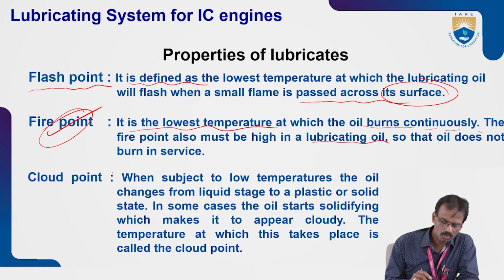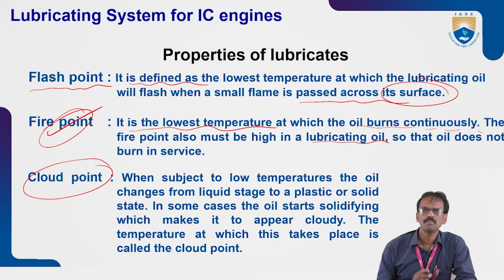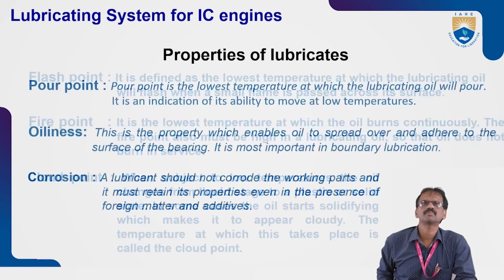Next, cloud point is also very important. When subject to low temperature, the oil changes from liquid state to a plastic or solid state. At a particular temperature, the liquid lubricant is converted into a solid or plastic state. In some cases oil starts solidifying, which makes it appear cloudy. The temperature at which this takes place is called the cloud point. These are very important properties.